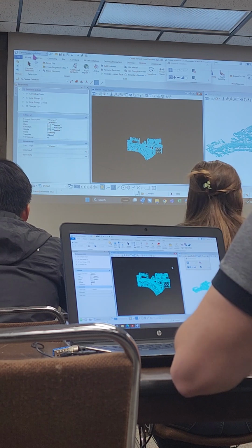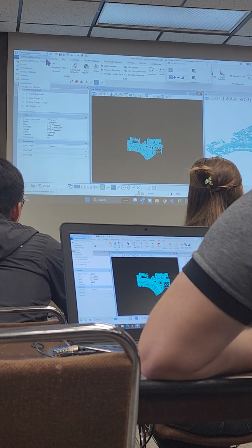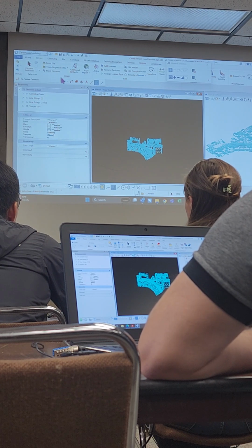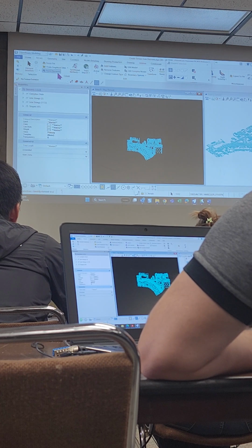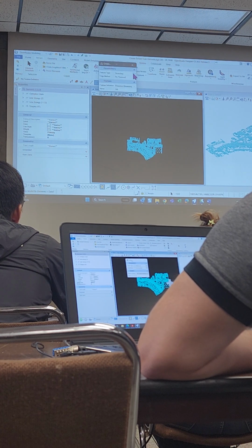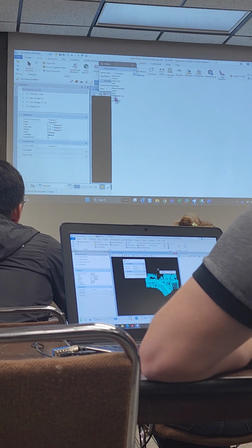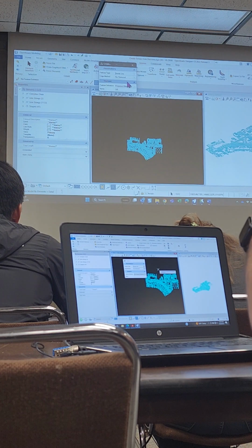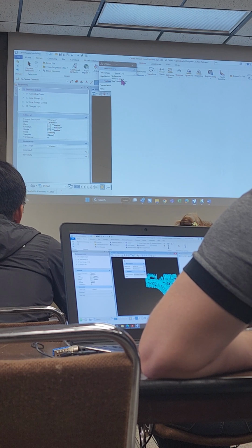And then we're in our terrain tab. So if you're not in the OpenRoads modeling workflow, go ahead and go over there. And then we're going to go to the terrain tab, and under create, we're going to go create from elements. Now for this, I'm going to choose break line for all of these. And then for the edge method, I'll choose remove slivers.